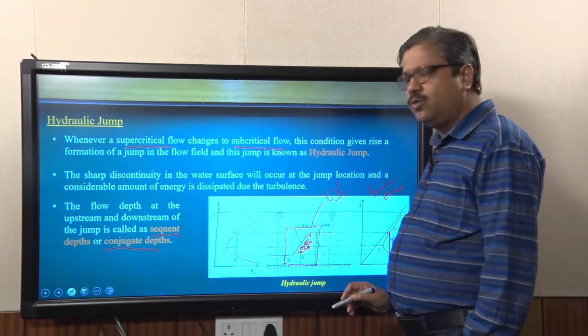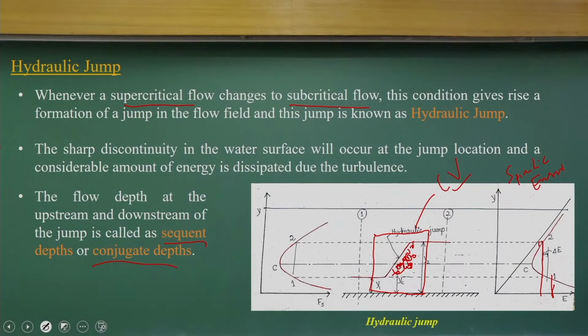On this surface there is no force acting, and at the bed there will be frictional forces, which in short reaches we can consider zero or negligible. Here I consider the pressure distribution to be hydrostatic, which is quite valid if there is no curvature of the free surface.